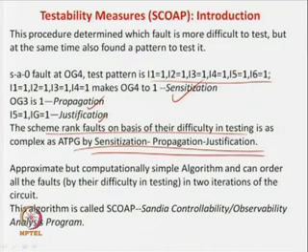So, difficult faults will go to sensitize, propagate and justify approach, and easier faults will go by random pattern generation. But now this algorithm in the last slide actually finds out which is an easier to test fault and which is a difficult to test fault, but for that you are using a very complex algorithm, that is sensitize, propagate and justify approach, and then you are finding out which is easier and difficult. So, I may say, why do you want to classify them as difficult and easy, when you can apply sensitize, propagate and justify approach, and you get the difficult faults as well as the test patterns. So, using that high complexity algorithm to find out which is the easier fault and which is difficult does not solve our purpose.